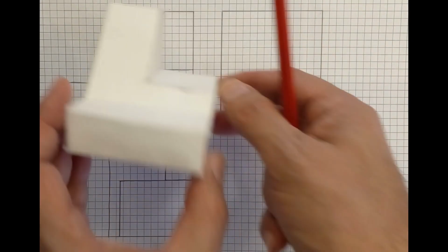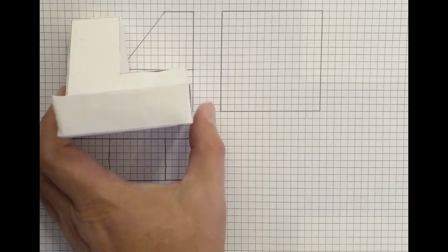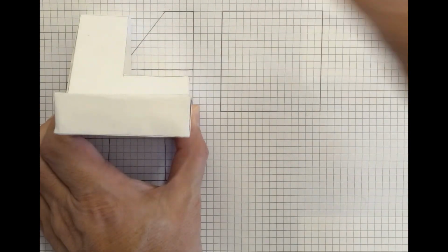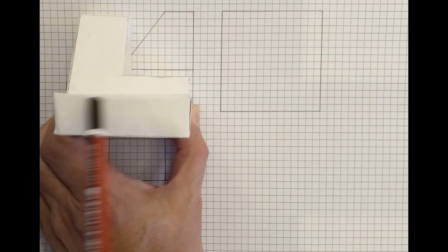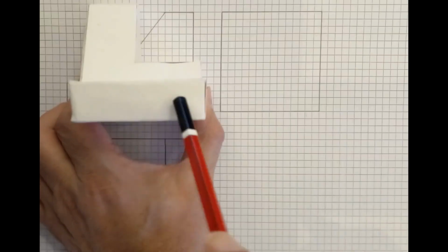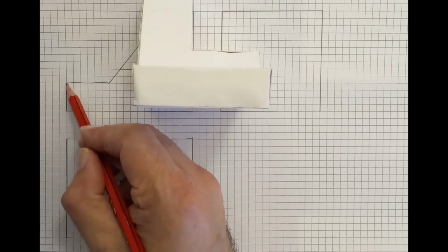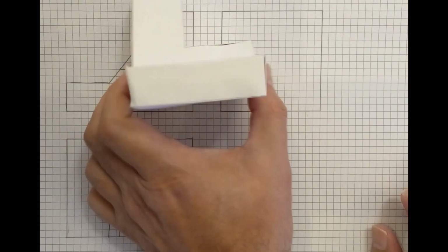So let us go now for the left side. The left side view is looking at the part from this direction. So this is the right border, this is the top border, this is the left border, and this is the bottom. From the bottom we have here a rectangle. Because this rectangle is perpendicular to our side, it is represented by a rectangle with its true shape and true dimension in the side view, while in the front and the top view it is represented by 2 lines. These lines are this one and this one. Of course the length is the entire length of the side view.